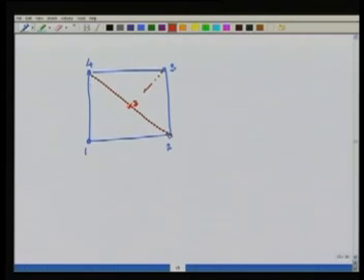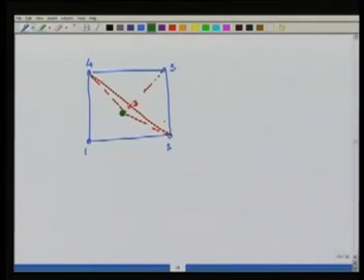If I go beyond this, that is, if point 3 moves to this point here, then the Jacobian will be negative at some points. Such quadrilaterals, for which one of the angles becomes an obtuse angle, are not allowed. One has to be very careful when making the mesh that I do not get this kind of quadrilateral domain.